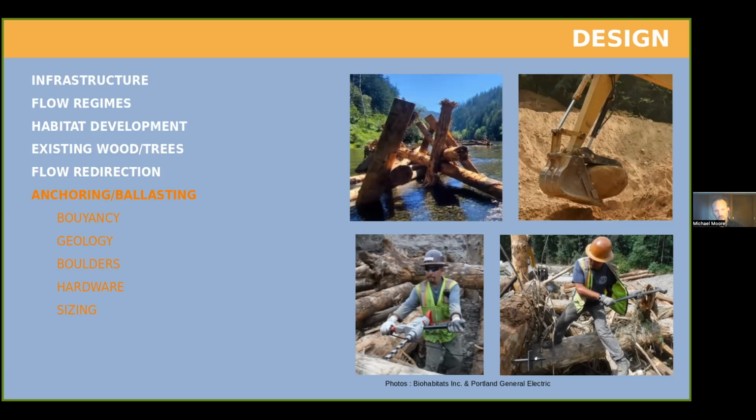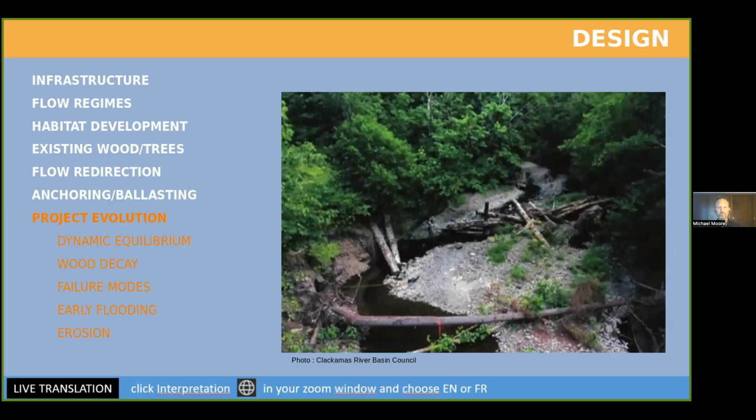So looking at buoyancy, looking at the geology, understanding if bedrock is going to be a limitation in the vertical direction in terms of implanting piles. Are we going to be using boulders exclusively for ballast, or is there a requirement for hardware? And then what sizing will we need to be using? And then project evolution, right?